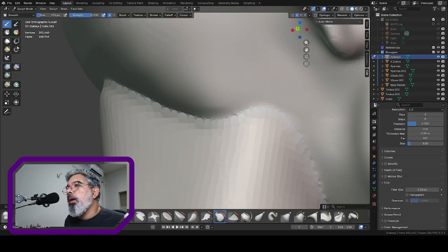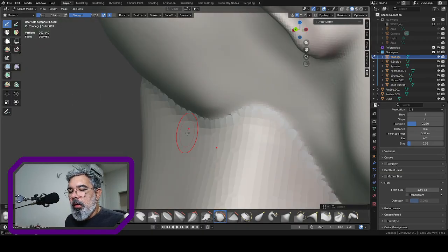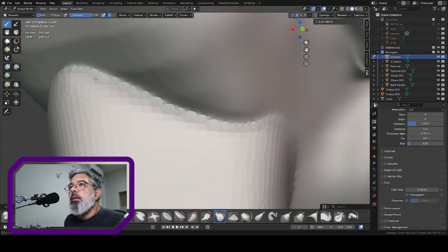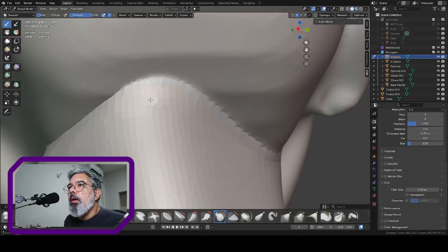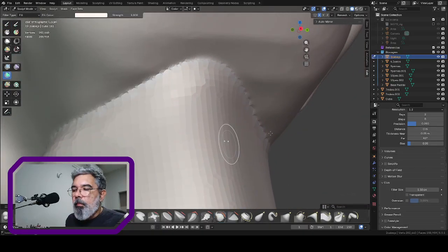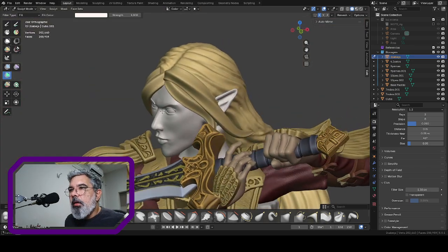It comes from outside, makes a loop inside and comes back out, and you just see the crease between that loop, and inside you have positive normals. When this happens, the Boolean doesn't work. This inside loop usually makes a problem when you try to Boolean, and it's probably happening here, and I will show you how to fix it.